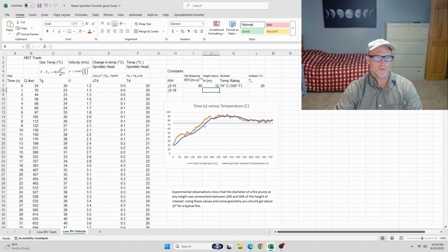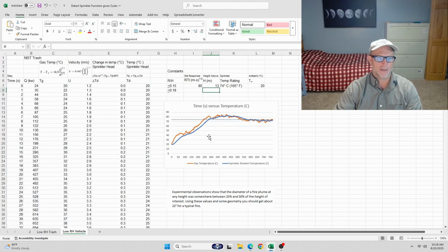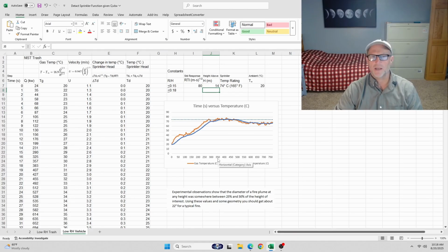So you can see I do activate after about 4 minutes in that case at 12 meters, 13 feet. I'll activate again at a little over about 4.5 minutes, and you go to 14. I'll activate at 14 at about 6 minutes, thereabouts. So that's a relationship. But when you jump from 14 meter high ceilings to 15 meter ceilings, they'll never trigger. It'll never happen.